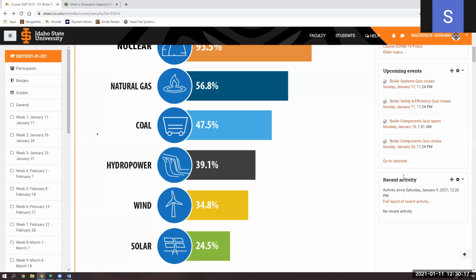So one of the big reasons coal and natural gas are so far behind nuclear in capacity factor is that even though they're not very agile at coming up and down in power, they are way, way more agile than nuclear. So we can choose to reduce the output in our coal and natural gas plant a lot easier than we could in our nuclear plant. So they could reach capacity factors close to 90% as well. We could operate them that way.